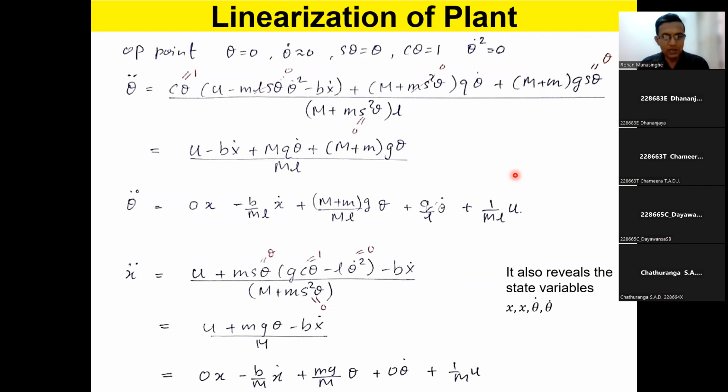We know how to deal with linear plants, and the plant is nonlinear now. Why don't we convert it to a linear model? That's what we do. And when you do that, you have to be very careful. You can't just convert a nonlinear plant to a linear plant, right? You can't change the physics of the plant.